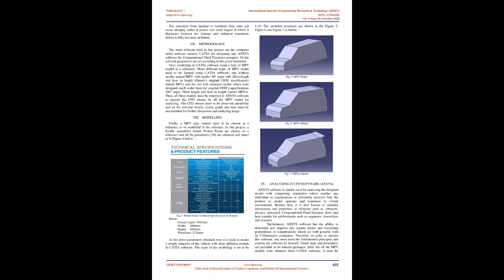Modern road vehicles such as cars have a coefficient of drag, CD, from 0.2 to 0.48. The smaller the value of CD, the better the aerodynamic flow of the vehicle. In general, the blunter the vehicle, the higher the drag coefficient. As a result, the percentage of fuel efficiency gained from reduced drag is about half the percentage of drag reduction at highway speeds of 110 km/h.